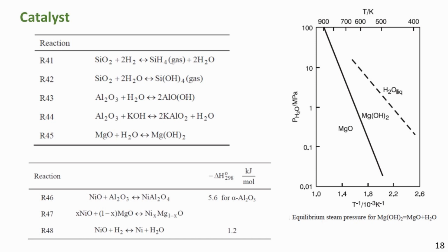the mechanical strength. While resistant to high temperature, catalysts based on magnesia are sensitive to steaming at low temperature because of the risk of hydration. The reaction may result in breakdown of the catalyst because it involves an expansion of the molecular volume. The equilibrium constant for the reaction is plotted in the right figure. It is seen that at the pressure typical of tubular reforming, hydration cannot take place at temperatures above approximately 350